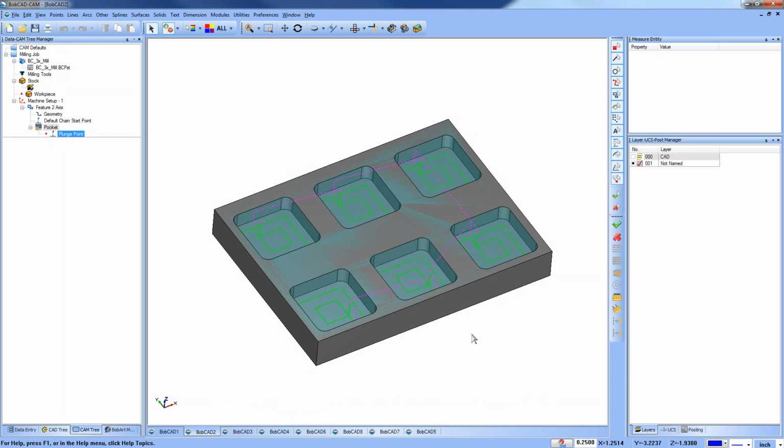So whether you're cutting a single pocket or multiple pockets, Mike's saying I use the percentage control, but it won't always be exactly the same. It's true with an offset routine or a zigzag routine, your tool engagement could be greater. What I would recommend you do, Mike, is use the adaptive tool path. That will give you a more consistent tool path step over across your pockets.